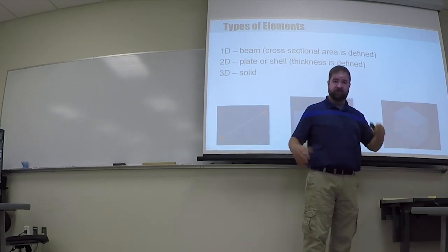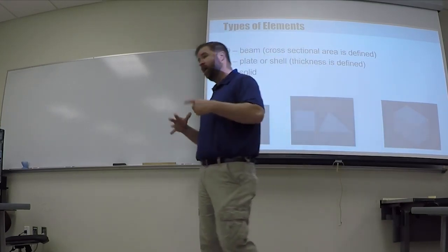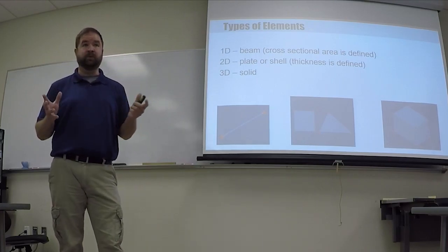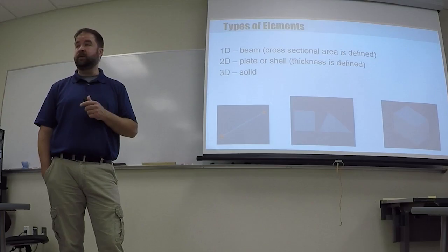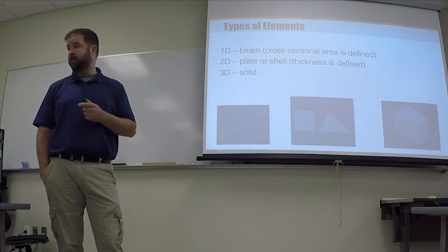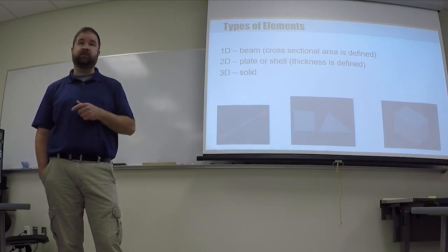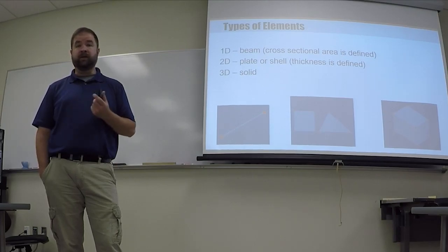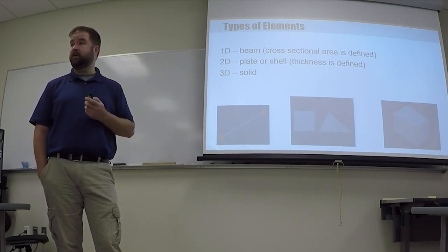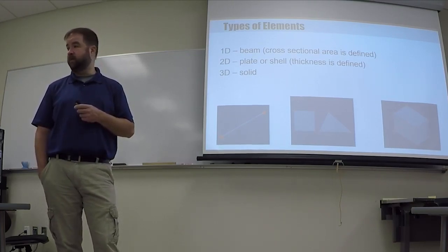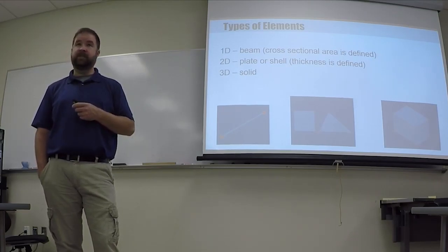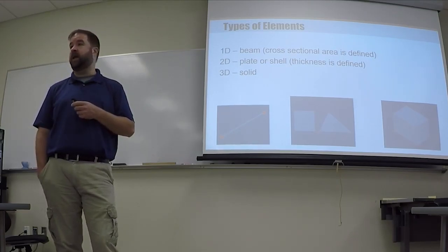And so if we're doing something simple like what most of our assignments are going to be, it's probably not going to make a big difference because what we're doing is so small that you can make it really accurate, make it really complicated, and it's not really a time premium for you. On the other hand, if you're trying to model that entire airplane, you better understand the types of elements that you're doing, because if you try to model that airplane with solid elements, then you're probably going to create terabytes of files, and it's going to take days or weeks to solve it.